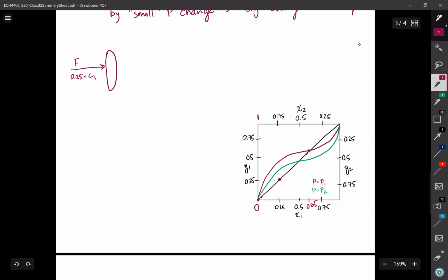So if I just took this portion of the equilibrium diagram and zoomed in on that, it kind of looks like something that we're used to, like with the magenta line. So I can go ahead and design this distillation column just taking into account that my XD is going to be approximately azeotropic. XD is the composition of the distillate product. And for pressure swing distillation, I'm going to do something a little strange and specify a partial condenser. We don't typically do that, but hopefully the reason why will become clear as we go through today.